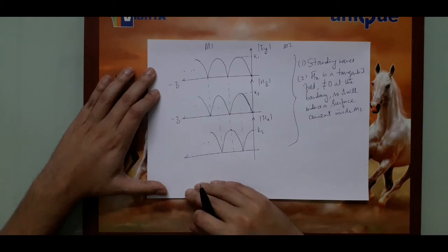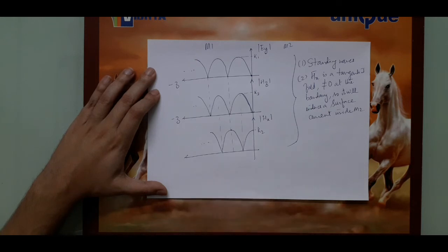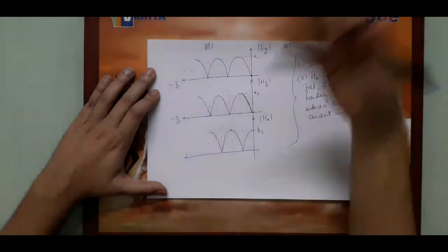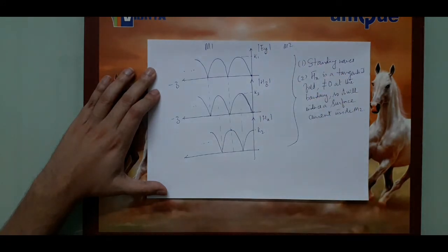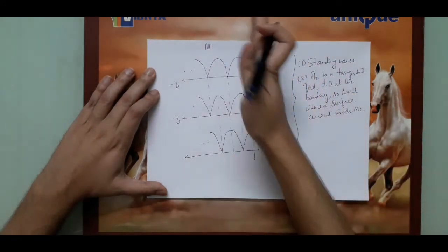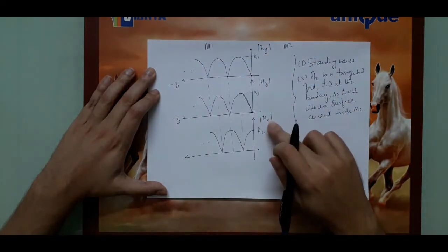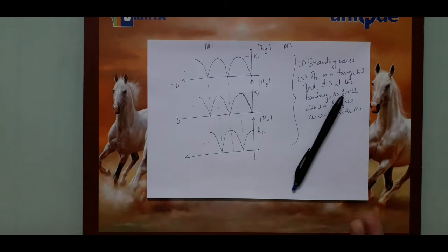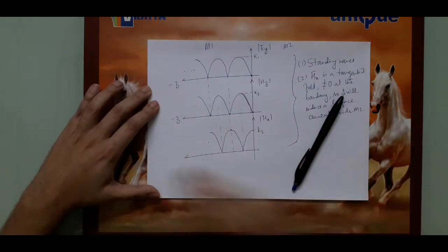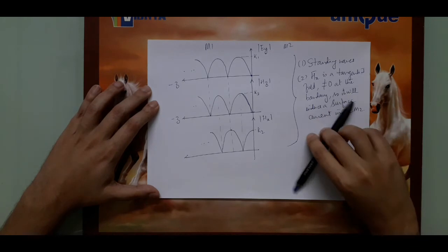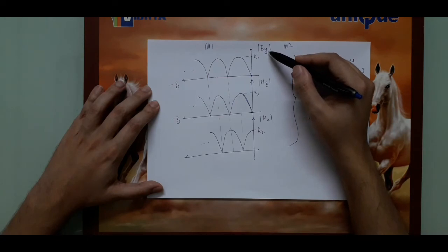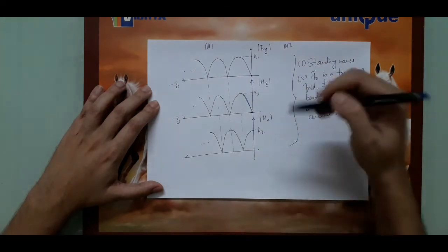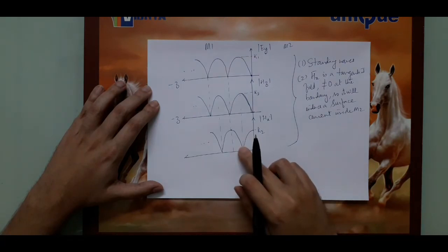So now let us talk of power transmission. When we talk of power, we can talk of E and H fields. So let's compare Ey with Hx. If I have the y component of the electric field and the x component of the magnetic field, as per Poynting's theorem, I can expect some power to flow along the z-axis, either this way or this way. That does not matter. If you see Ey and Hx, they are 90 degrees phase shifted from each other.